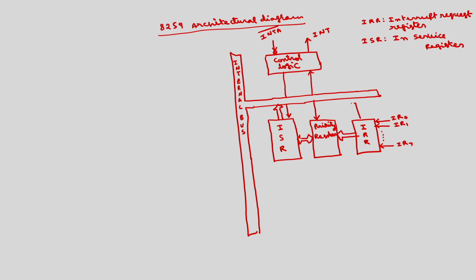Then we have the interrupt mask register. You have to mask some interrupts whenever more than one interrupt requests the use of the interrupt of 8086 or any microprocessor.